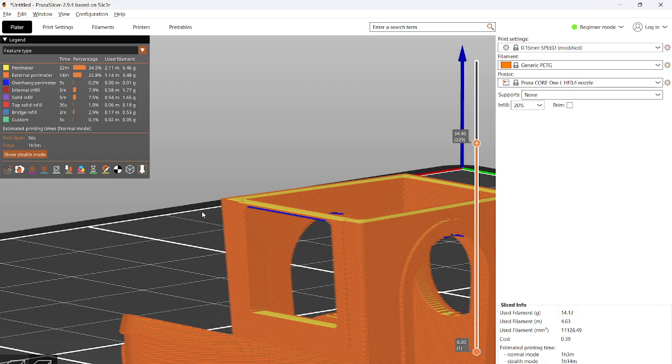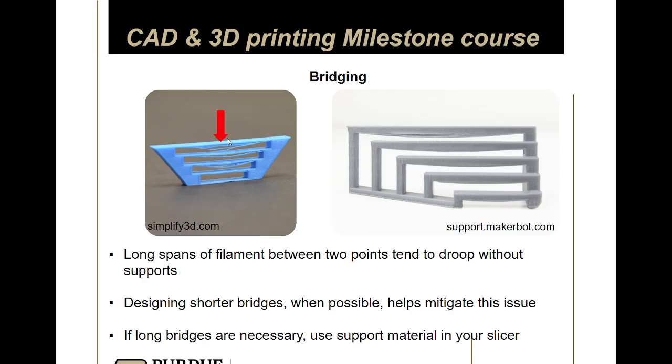When you print the 3D Benchy, you typically don't have supports, but you have this big span that doesn't have anything supporting it underneath. And 3D printers can reproduce this with a good tune and making sure that the bridge isn't too large.